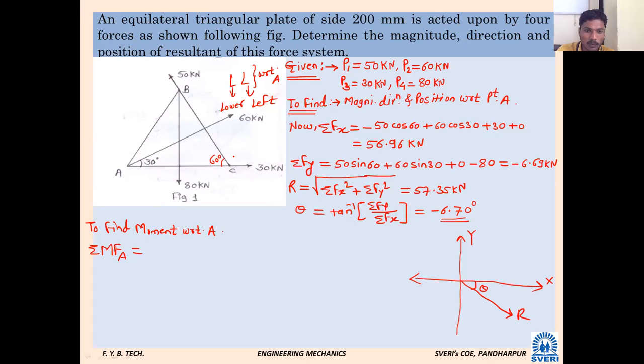It's better if I divide this force here in this way. So I will give the name 50, what will be that angle? Vertical 50 sin 60, no? Okay. Are you with me? And the x component will go in this way, 50 cos 60. I have resolved at point C. Any problem? No, sir.